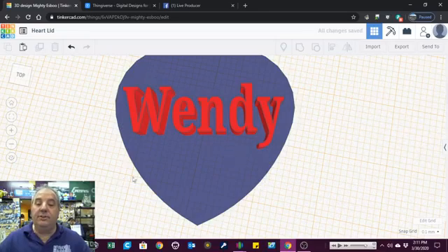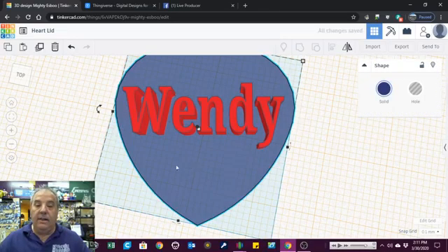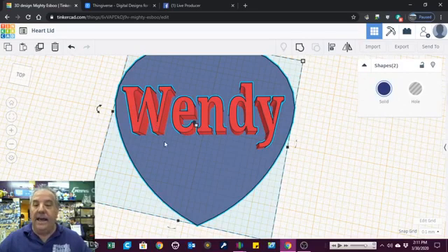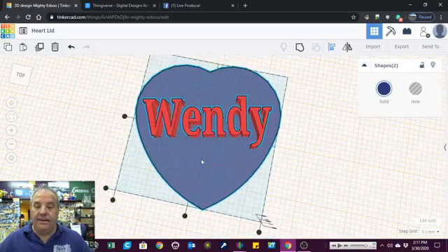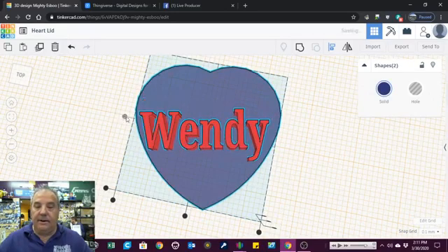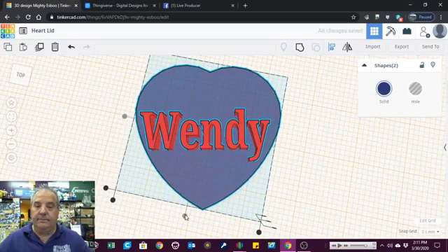I can then grab in the middle there and center it. Back to what Steve was showing last week. I click on the outside, I hit my shift, and then I have both of them highlighted, which brings up the centering tab here. I hit center, and you'll see it brings up the dots. I'm going to bring it to center there and there. Okay.